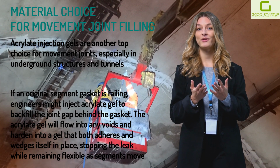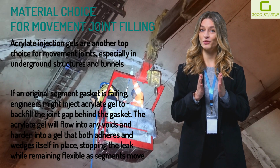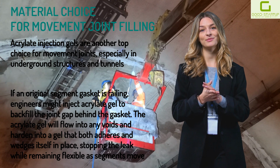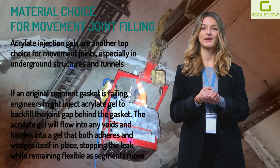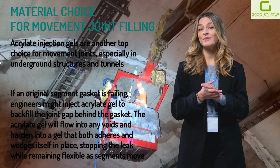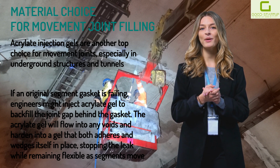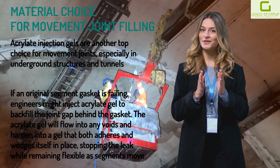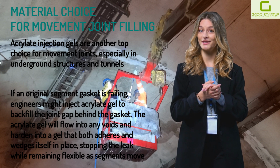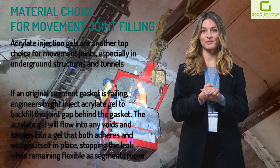Acrylate resins are very low viscosity, almost like water, allowing them to infiltrate fine joint gaps or surrounding soil before gelling. They are typically injected as two-component systems. The components mix and then polymerize into a gel. The key advantage of acrylate gels is their combination of flexibility and hydrophilicity. Once cured, an acrylate gel stays rubbery and can accommodate joint movements, and it also exhibits pronounced hydrophilic swelling. In contact with water, the cured acrylate will absorb some water and swell, enhancing its sealing performance.